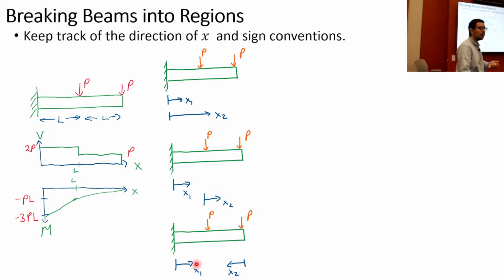If I'm thinking a little bit more about geometry or graphical methods, and trying to cut some work out, I will probably think about having coordinate systems from either side. This is another way you can do it. So you have 3 options here in terms of how you define the coordinate systems across the beam. And you are going to be looking at these coordinate systems and trying to make sure that you have appropriate ones as you get through different sections.